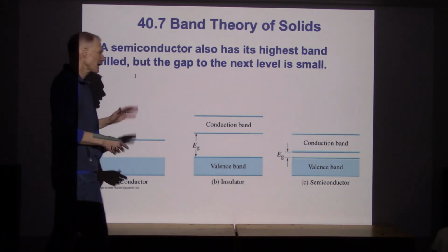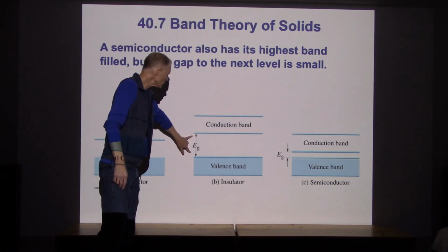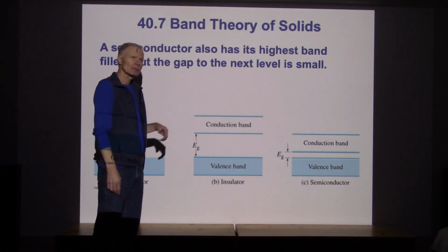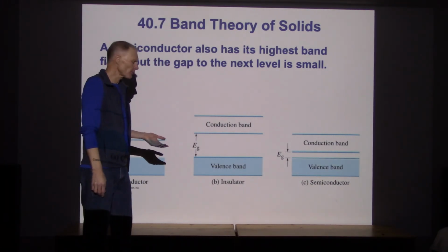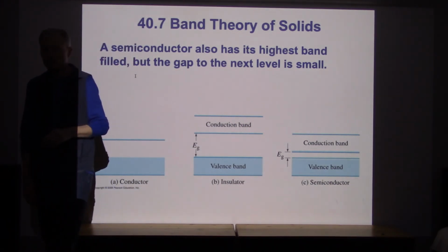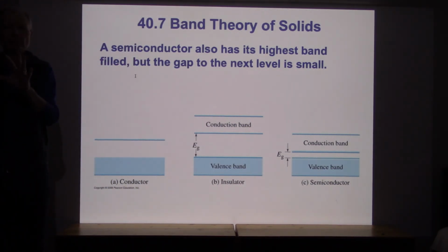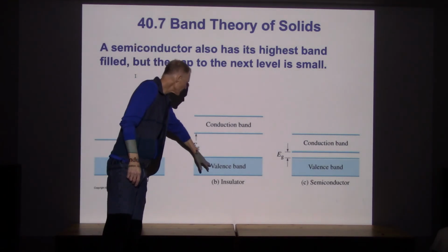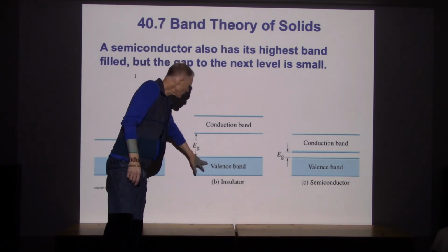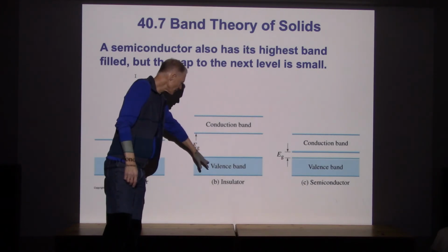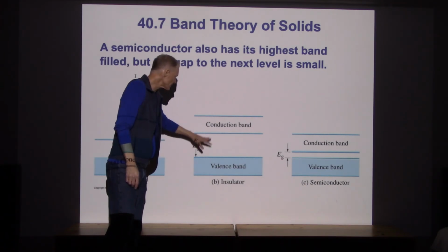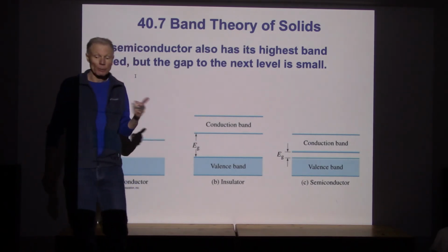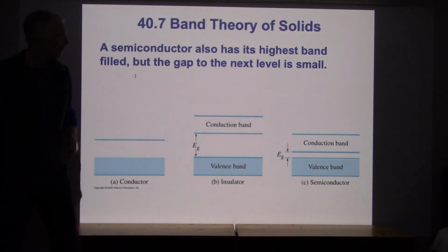And so that says the energy gap here is really large. If this wants to conduct a current of electricity, think diamond: can I take a piece of diamond and conduct electricity through it? Probably not. There's probably a sizable energy gap, or glass or something like that. There's a sizable energy gap between where the electrons have filled one set of states up to the next state that would enable conduction to take place.